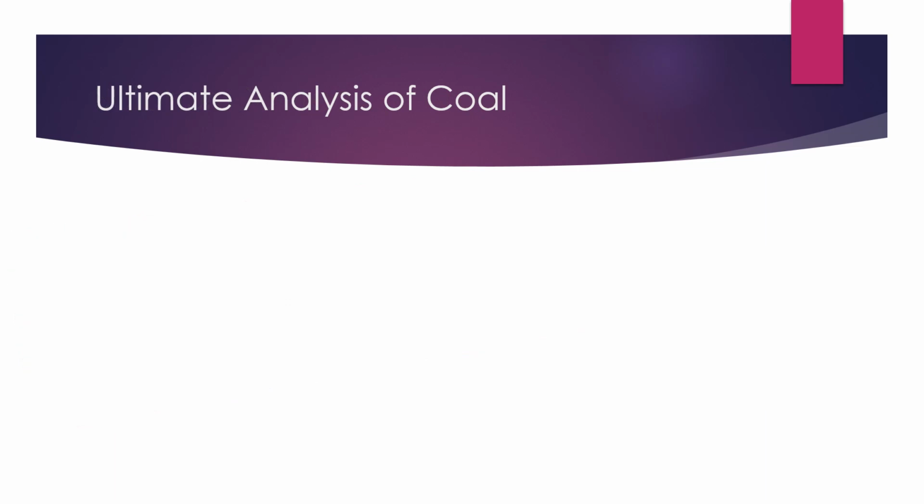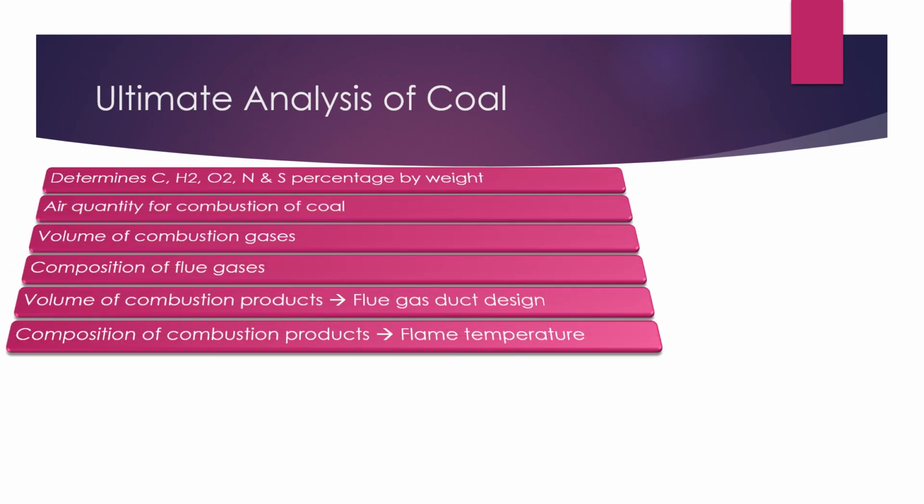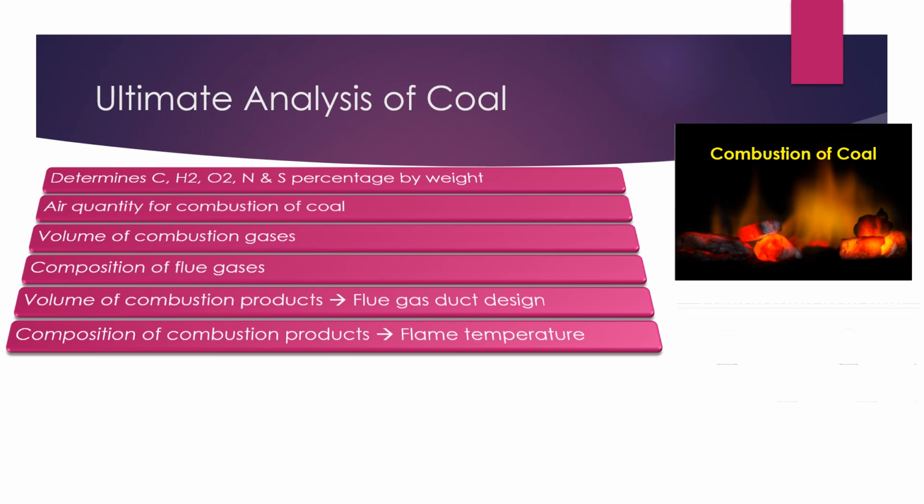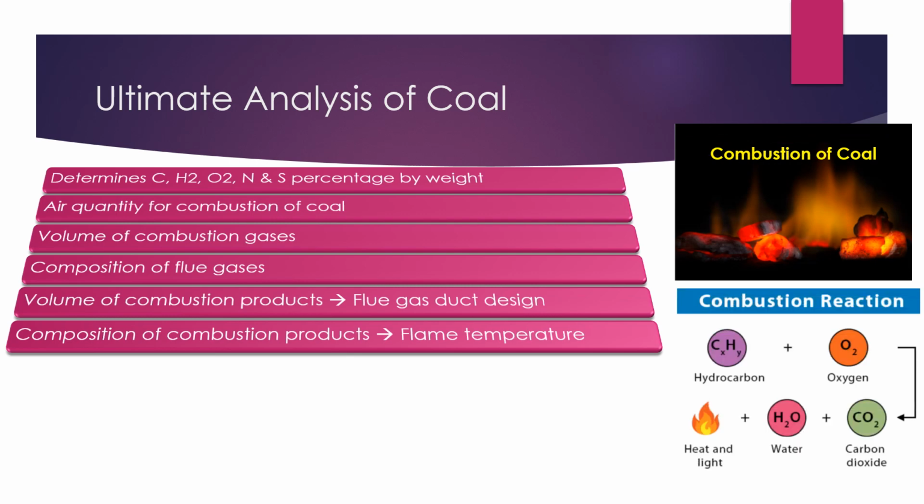Now, let us discuss the ultimate analysis of coal. In this analysis, we find out the weight percentage of carbon, hydrogen, oxygen, nitrogen, and sulfur present in coal. This analysis is helpful in determining the air quantity required for combustion of coal.